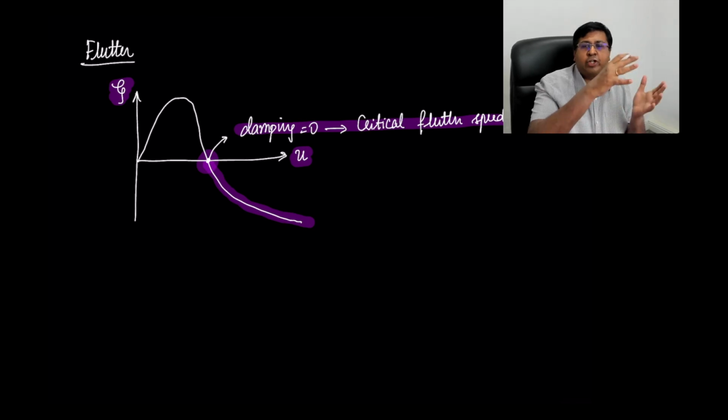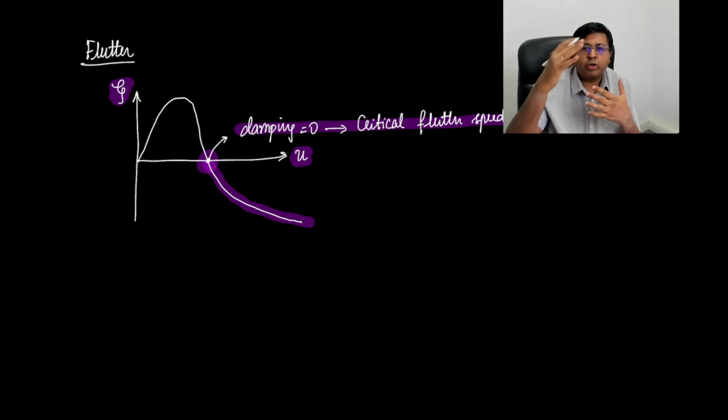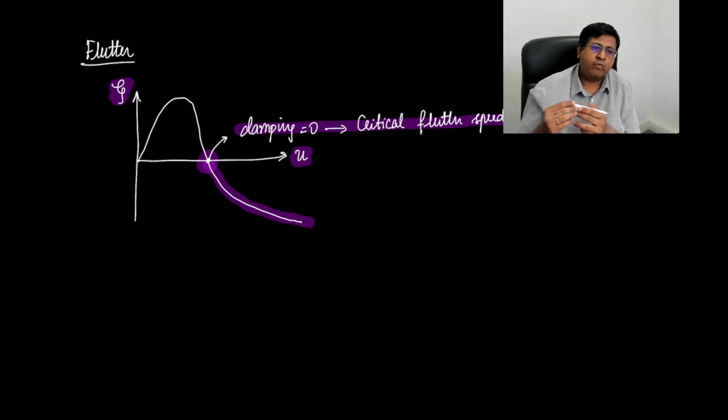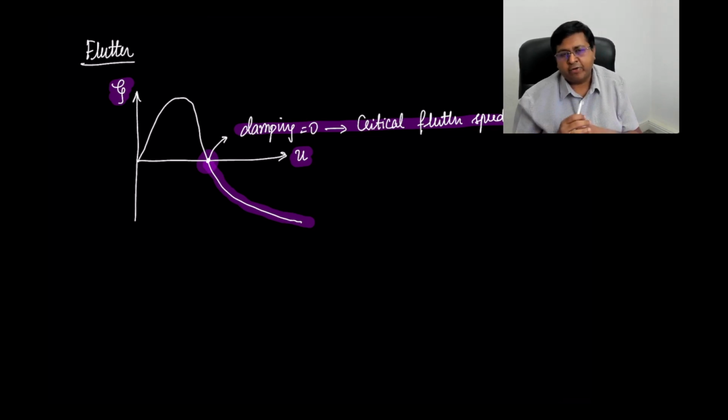As long as our damping ratio is positive, that means the oscillations in the system will damp out to zero. As soon as the damping ratio becomes zero or negative, the oscillations will start to increase very violently. And that is an intuitive, mathematical way that we can find the point at which flutter occurs. An aircraft designer should be able to demonstrate by documentation of design work and testing that the flutter speed is at least 20% above the dive speed. In order to get your designs through, that is a very important, simplistic criterion to see that flutter is not going to occur in these dive speed ranges.